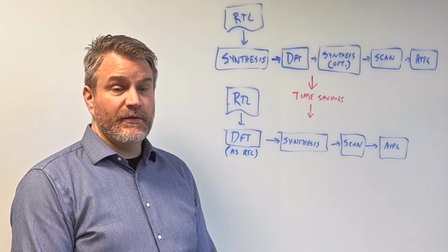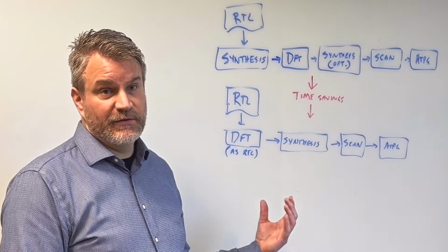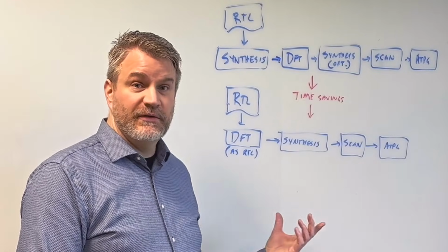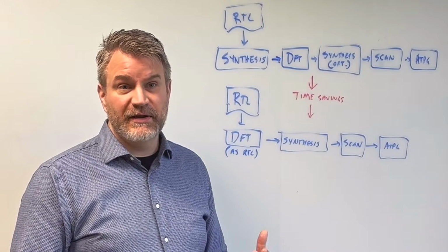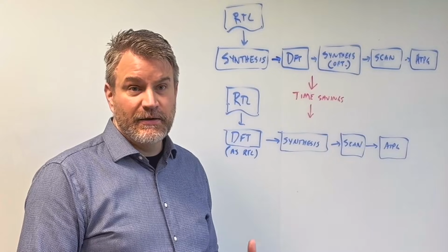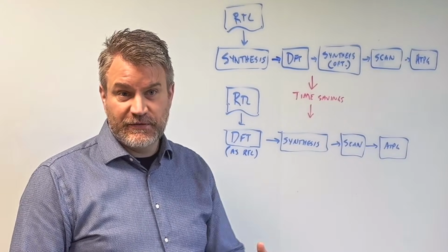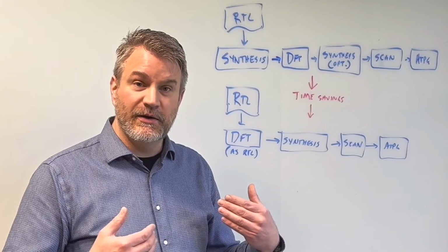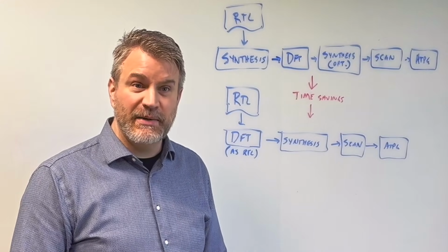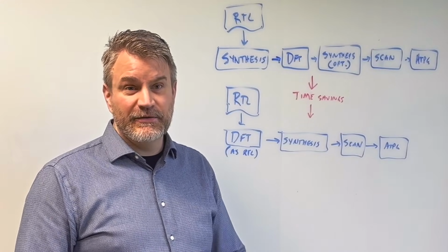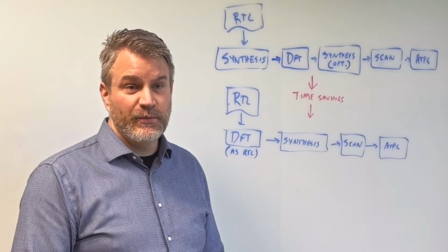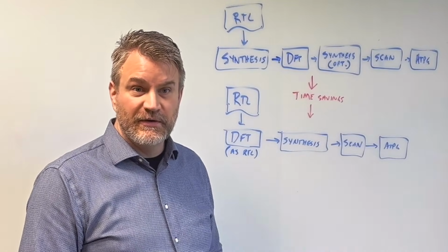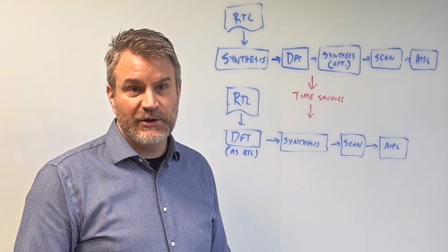Right. And quick synthesis with our products is an underpinning capability here. Because with quick synthesis, we have the ability to adapt tests on the fly. As the design changes, as you're looking to learn more about the estimated coverage and estimated pattern count of the design, as ECOs are made, we can run the design with DFT through quick synthesis and then check those numbers as we go.